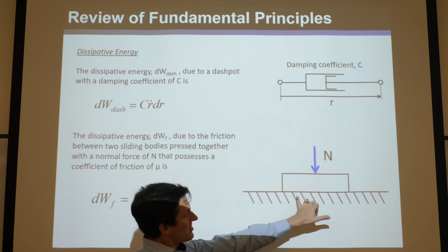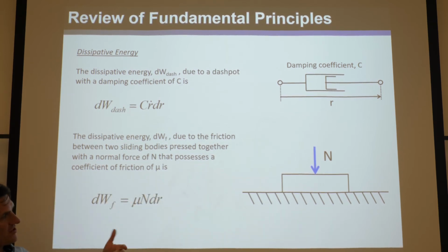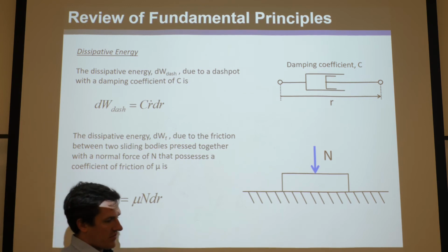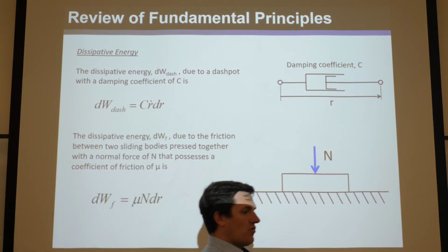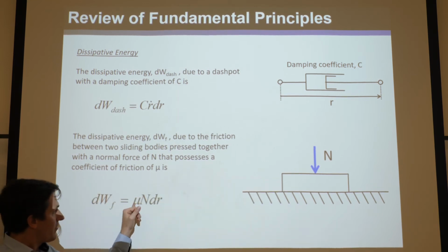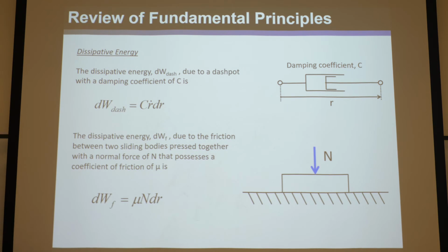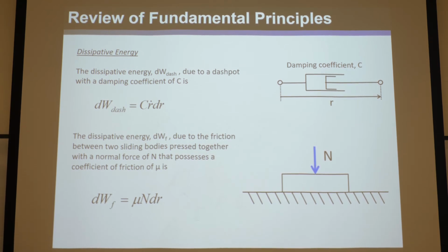And that force that it resists just before it slips is N times the static coefficient of friction. And then once you exceed that and push it beyond that force, as it starts moving it switches to the kinetic coefficient of friction, and that's a lower force, so it actually becomes easier to continue pushing something than to start pushing it.